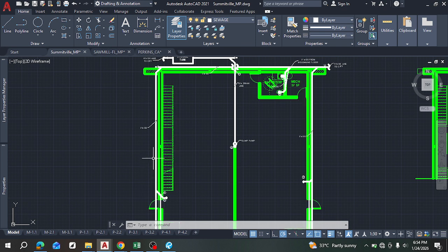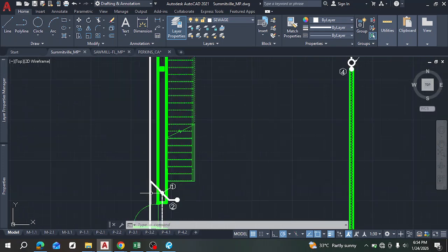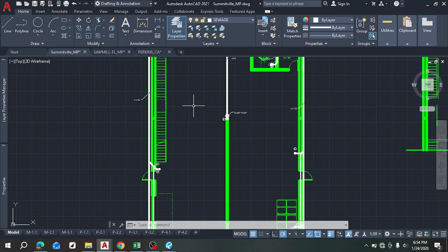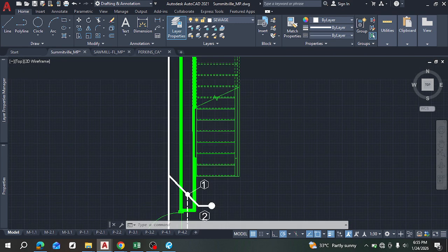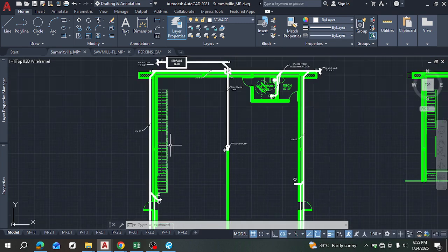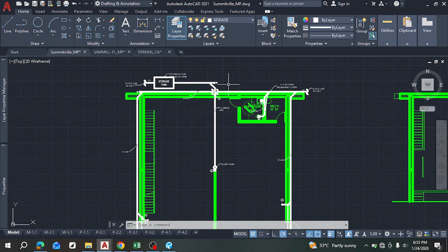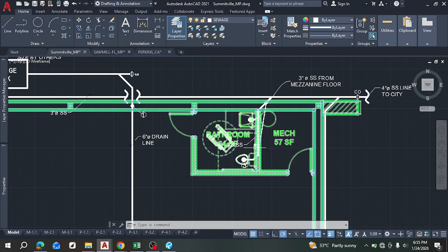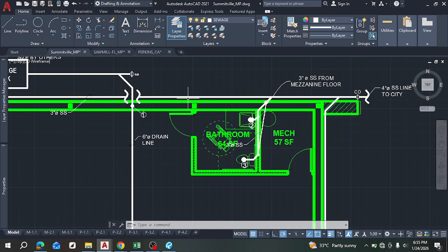Now you see that routing outside is a problem, because most times a grease interceptor is added at the point where it is at the point P. It's usually added along the line, right? And it could be added here, but that is not advisable. Another thing with a grease interceptor: don't add the flow from a bathroom or any other place that will contaminate the grease, it should not be part of the connection, right?